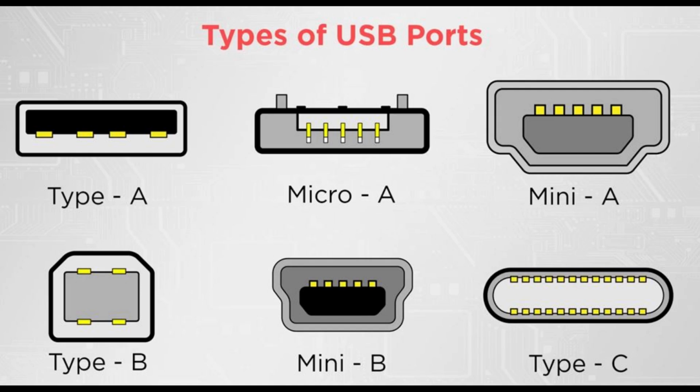The USB 3.1 specification introduced an enhanced SuperSpeed system, while preserving the SuperSpeed architecture and protocol, SuperSpeed USB, with an additional SuperSpeed Plus architecture and protocol, aka SuperSpeed Plus USB, adding a new coding schema, 128B/132B symbols, 10 Gbit/s, also known as Gen 2, for some time marketed as SuperSpeed Plus, SS Plus.